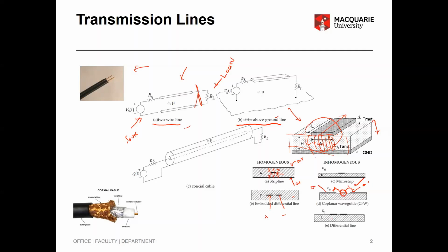And then you could have a coaxial cable, where the center conductor is the signal and the outer conductor is the ground. So the field goes from the center conductor to the ground, and the field is confined. So there's not much leakage outside. If you see things like the microstrip, you can have leakage, because the fields coming from the microstrip to the ground extend into the air as well. So you can have certain leakage, and it results in a certain loss as well.